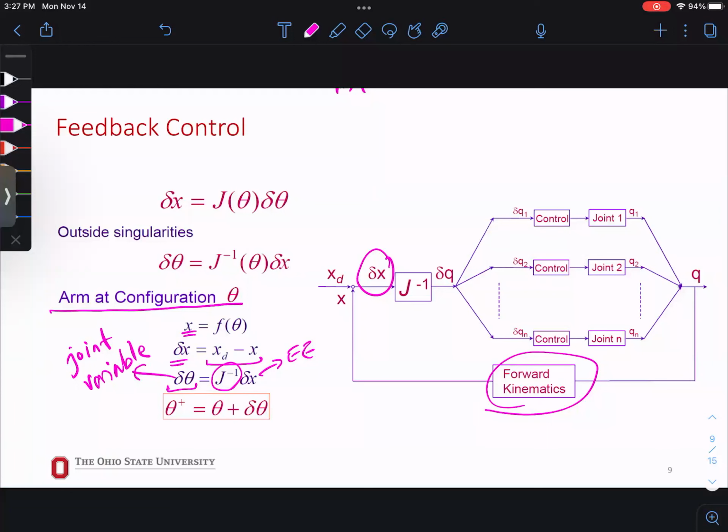All right. Now, this is your control law. Control law tells you that wherever your joint variables are, your initial theta plus the amount of change that you need to apply to the joint to get to your desired position. Why we are using theta as our control law? Because that's what we can directly change. These are our actuations, right? So this theta is a vector, like of each joint. We can manipulate each joint's position and get the whole system moving to a new state.